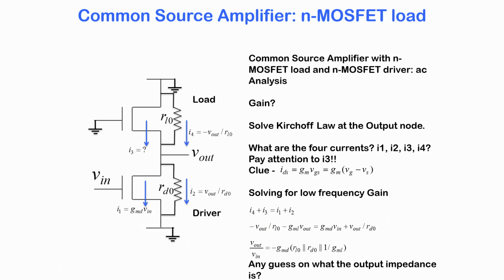So, the small signal analysis is like this. That was the load MOSFET, the load n-MOS transistor which is sitting in saturation. This is the channel length modulation resistor of that load, and this is like an ideal n-MOS transistor, and in combination they give you the non-ideality effect. The gate is grounded because this was a DC bias signal that we had applied. So, that is AC ground, and now we have a small signal AC V in into the driver MOSFET, which is also an n-MOS in saturation.